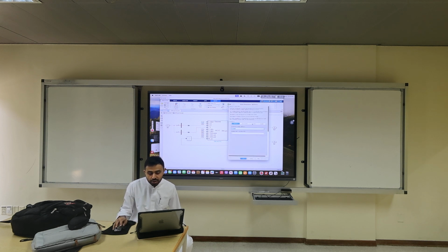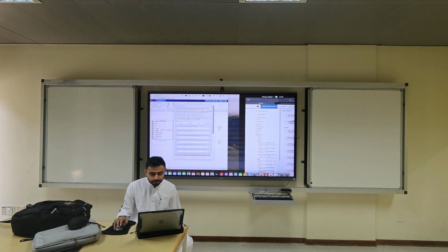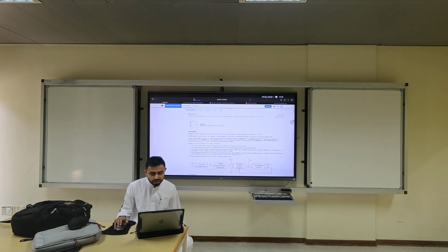So in the homework, maybe we'll ask you to change the regulator output gain to 200. See what will happen. Change the exciter field time constant to 0.3. Make it slower. Okay? Again, if you go back to the help page, it tells you all of these parameters.